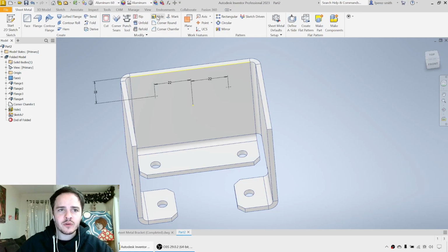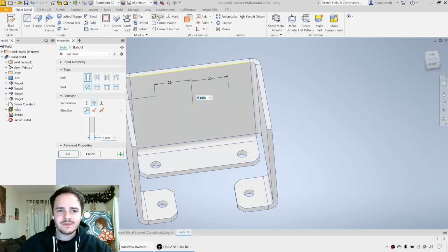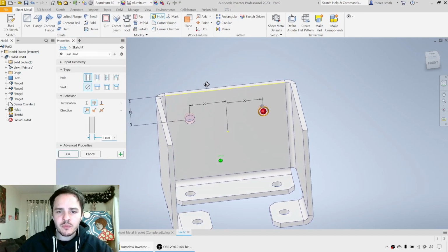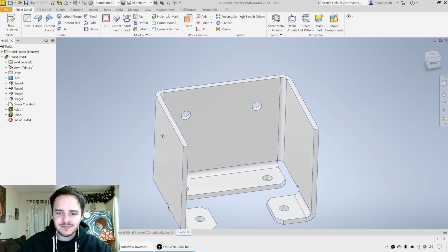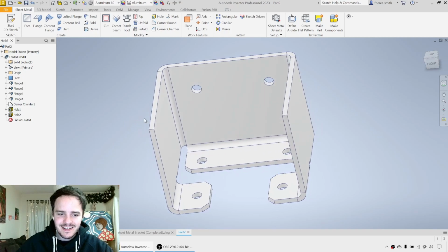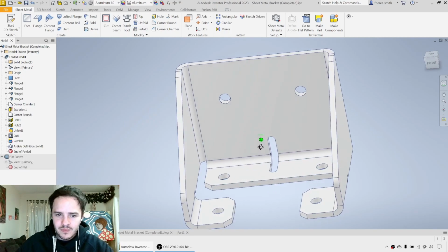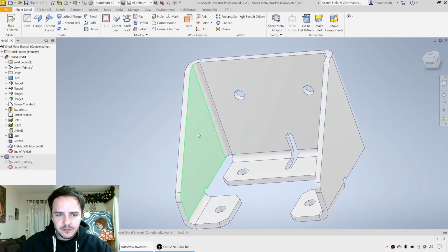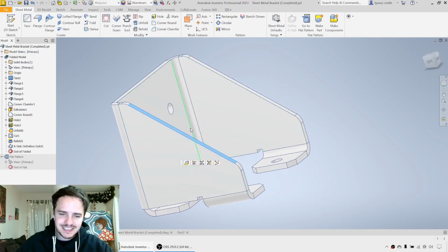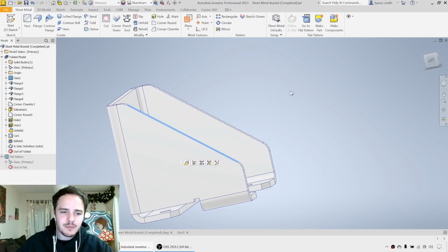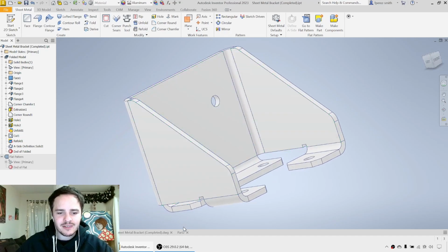And again, we'll create a hole using the hole command. Because these are the only 2 points that we've drawn, it will pick up on them automatically. And we can click OK. Excellent. Okay, home stretch. We've got 2 more things to draw. The first one is we have to cut out these triangular sections so that the flange is a bit more streamlined. So this works exactly like 3D modeling.